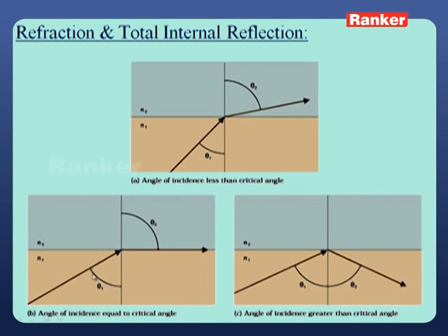This angle is very important. Up to this critical angle, it will take refraction into the clad. So from the core, it always takes refraction into the clad. Whenever we apply the signal with this critical angle, it is neither reflected nor refracted; it just coincides with the boundary. Right? Now I will increase this particular angle further.